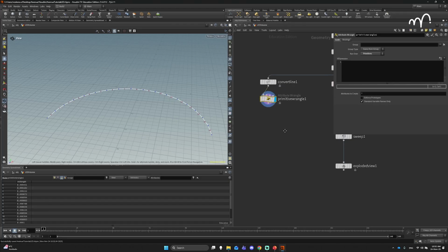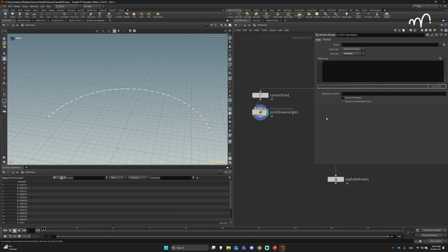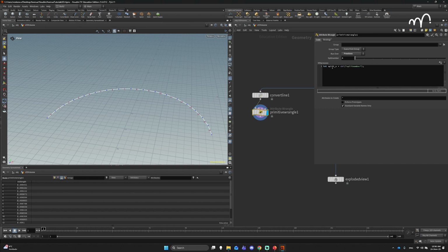So that's the explanation. Now let's go in here and create this inside of our logic for the wrangle. I hope this is visible, but we're going to create a new integer, which is going to be our split number. And that's equal to a new channel that we're going to create, which is going to be split number. Let's call it like this. Cool. So we can create the channel already by clicking on this icon. Now our split number is going to be this value here.